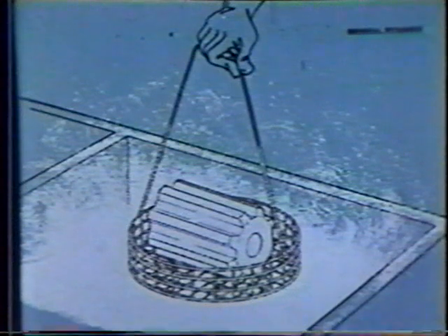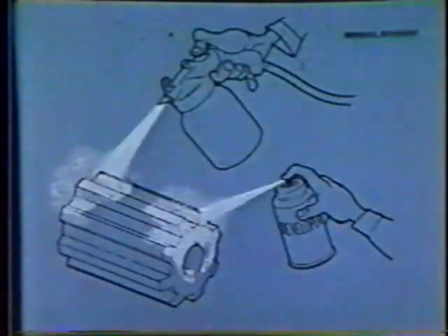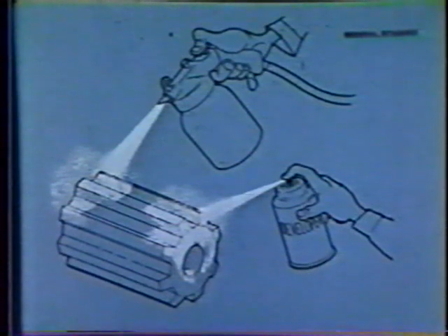When using dry powder developers, the specimen is dipped or dusted and the excess powder removed by gently blowing, shaking, or tapping. With non-aqueous wet developers, best results are obtained with a light and even spray that doesn't soak the test surface. Developing time also is important. It must be long enough for indications to develop, but not so long that they become blurred or distorted. Using water-based developers, the time in the drying oven is usually sufficient. Using dry or non-aqueous wet developers, the accepted norm is 7 to 30 minutes.